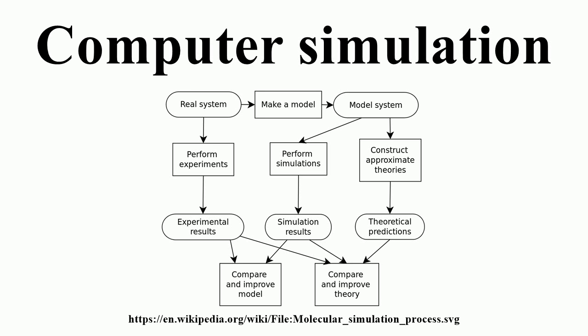Simulations which store their data in regular grids and require only next-neighbor access are called stencil codes. Many CFD applications belong to this category. If the underlying graph is not a regular grid, the model may belong to the mesh-free method class. Equations define the relationships between elements of the modeled system and attempt to find a state in which the system is in equilibrium. Such models are often used in simulating physical systems, as a simpler modeling case before dynamic simulation is attempted. Dynamic simulations model changes in a system in response to input signals.